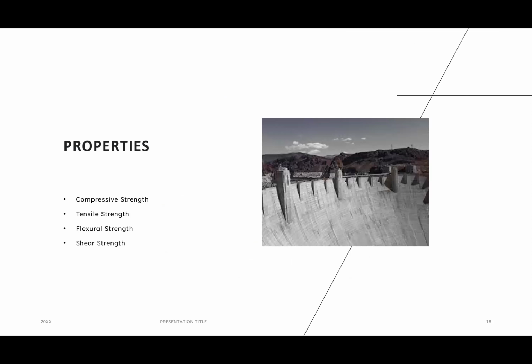So moving on to properties of concrete, the first one is compressive strength. Compressive strength is the ability of a material or structure to carry the loads on its surface without any crack or deflection. A material under compression tends to reduce in size, while in tension, size elongates. Compressive strength of concrete depends on many factors such as water-cement ratio, cement strength, quality of concrete material, quality control during the production of concrete, and even more. Concrete compressive strength for general construction varies from 2,200 psi to 4,400 psi, and higher in commercial and industrial structures.